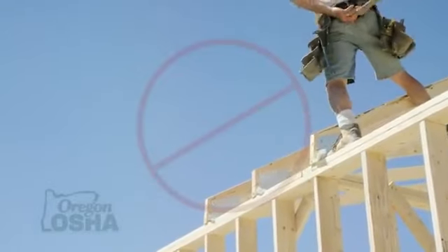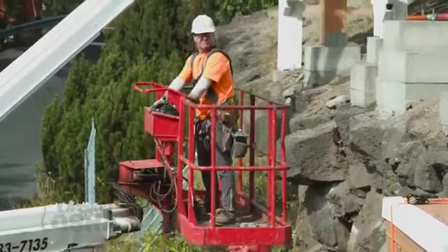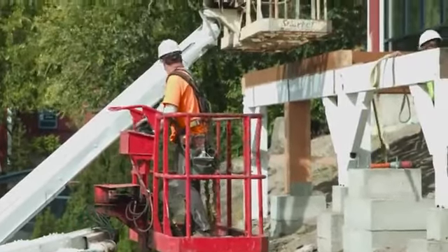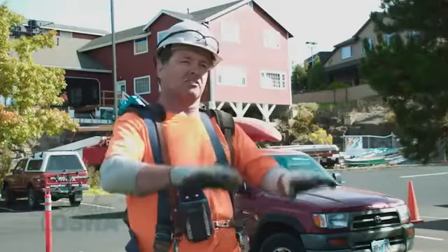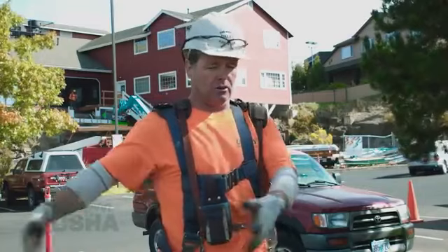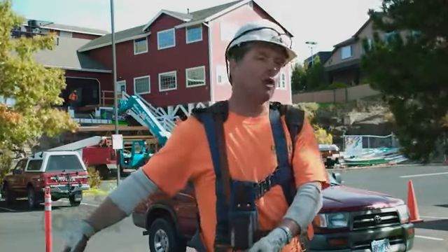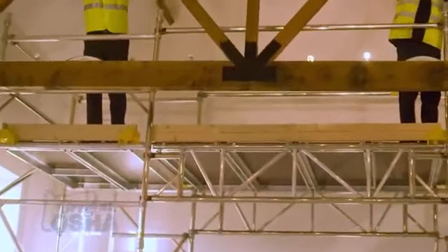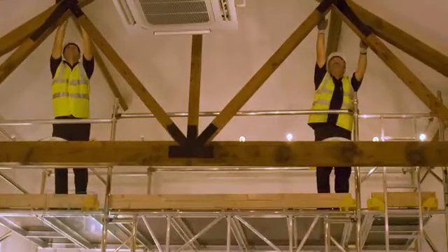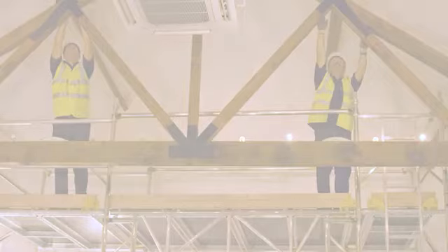Now we work off of scissor lifts, man lifts, whatever, and the guy's near plate height, but the plate is actually mid-chest or stomach because he's on a scissor lift, and you can roll the trusses that way. And you have a nice platform to have all your blocks. Or you could build scaffolding, but scaffolding has its own inherent pitfalls too, because you've got to build it right.